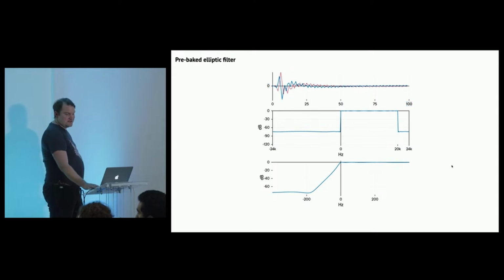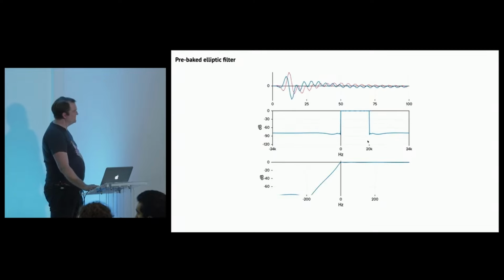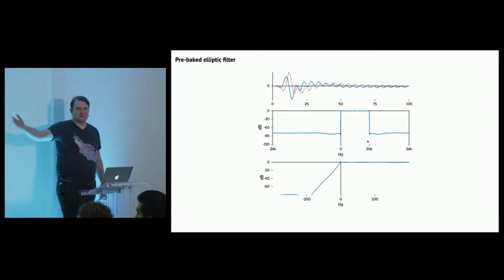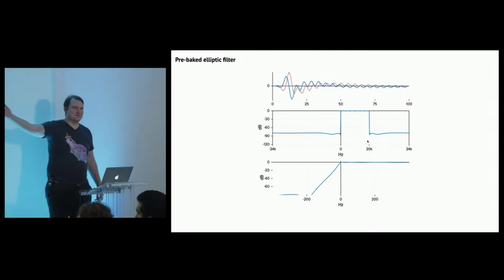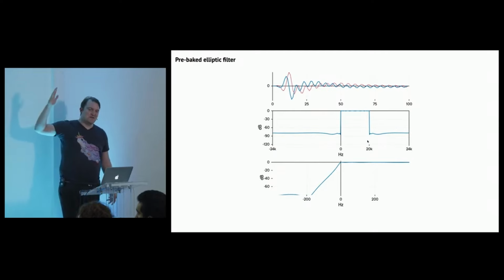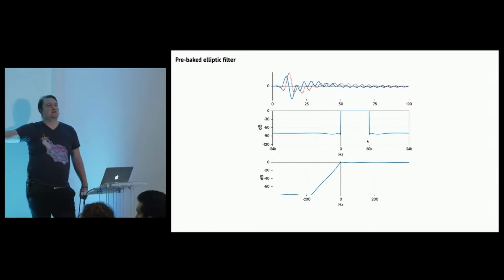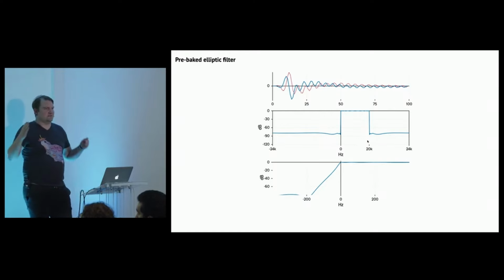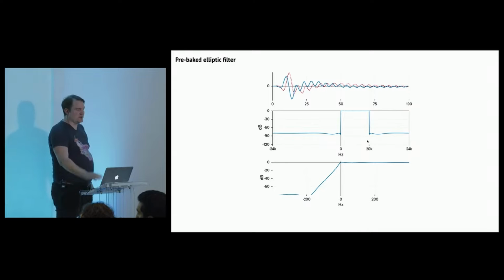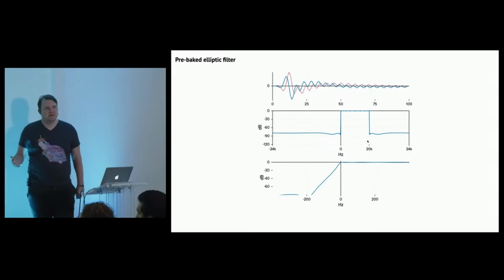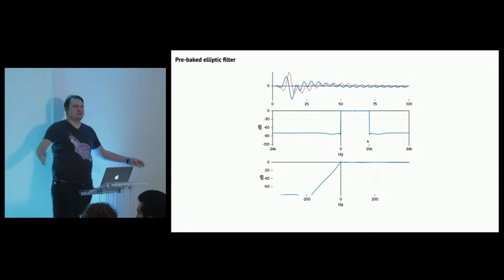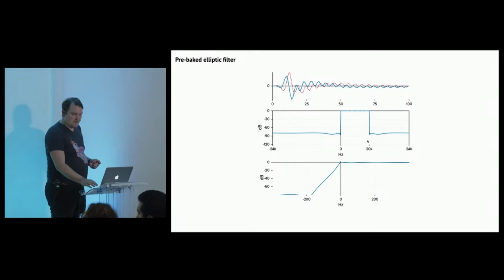Then you can see the same filter class running at 96K, in this actual real working example plotted from C++ code, what it is doing for a higher sample rate. It's keeping less of the spectrum, but that transition at the bottom is still the same width, because we're not making our pass band wider.